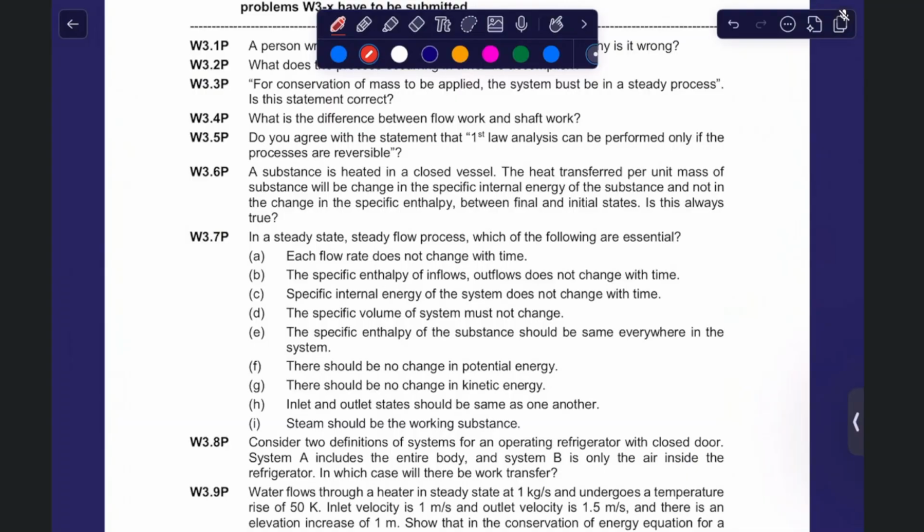But delta U, the change in internal energy, shows the energy change. Therefore, if the volume does not change, and there is no other kind of work such as boundary work from a moving piston, heat added equals the change in internal energy.